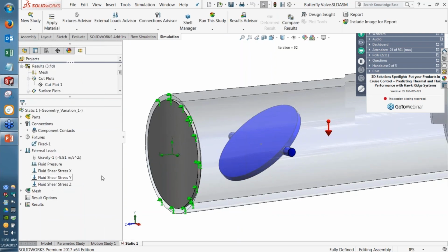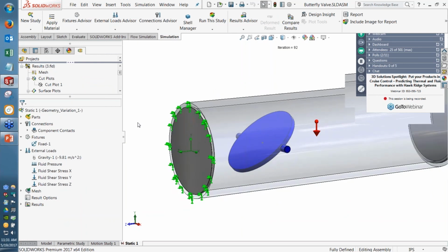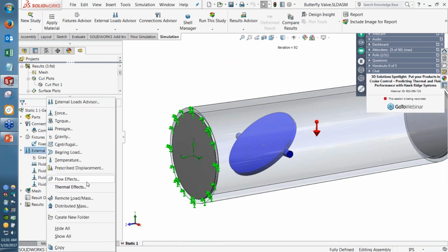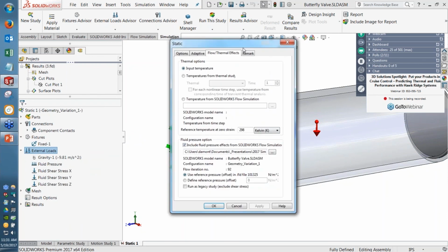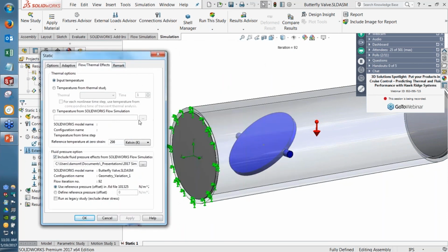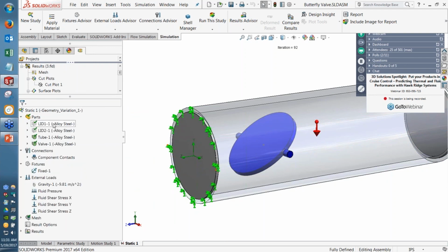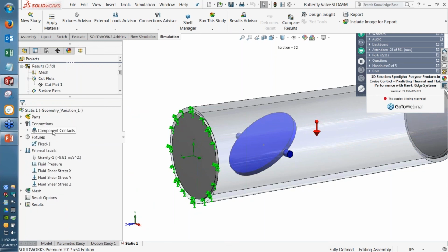We can create this mesh as well, which is going to look a little different because this is a finite element mesh for our structural analysis tools. You can see it's automatically generated using, in this case, solid tetrahedral elements. If I hit run, I'll get some results, in this case stress and displacement. I can animate these, of course. It looks like the stress would primarily be concentrated in the hinge of the valve itself, the pin that fits into the shaft. And I can see how much the valve itself displaces under those loads as well.